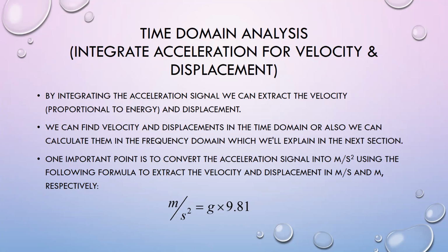But in the time domain, there is a problem, and most of the time when you calculate the velocity and displacement, since there is a lot of noise in the real world, and when you record the data, definitely you will record some noises from the environment of your system. So when you calculate the integral, definitely we will have an error in the velocity, and especially when you calculate the displacement, because you will have double integration, and 2 times you should calculate the integral. So your error will be more than the velocity, and we need some methods. For example, we can use filters to vanish these noises.